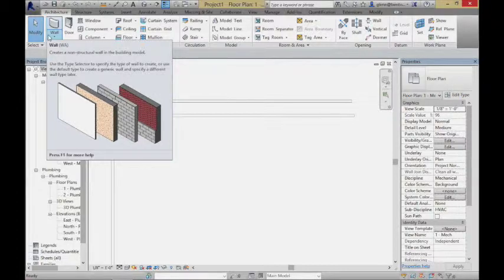Or even, in a lot of restrooms, which is really kind of cool these days, you'll go into the restroom and there'll be a urinal or something, but it'll be something like this. The urinal will be hanging out here on the wall, but there'll be this little shelfy space on top of that. You sort of wonder what that little shelfy space is all about. The reason it's there is that all the piping is running around inside this space, and we have good mechanical access to it. We can pop that shelf off and take care of everything. It's just trying to provide some mechanical space.